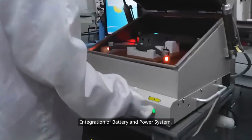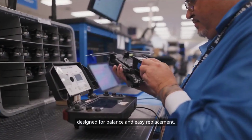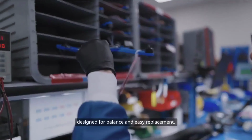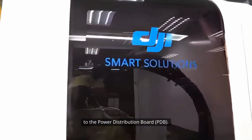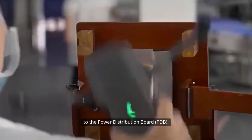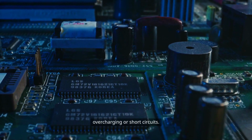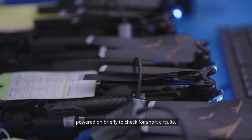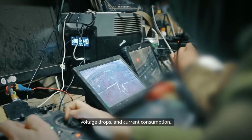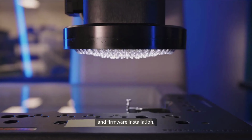7. Integration of battery and power system. The battery compartment is installed and designed for balance and easy replacement. The power system includes connection to the power distribution board, PDB, voltage regulation modules, and safety circuits to prevent overcharging or short circuits. When the system is connected, the drone is powered on briefly to check for short circuits, voltage drops, and current consumption.